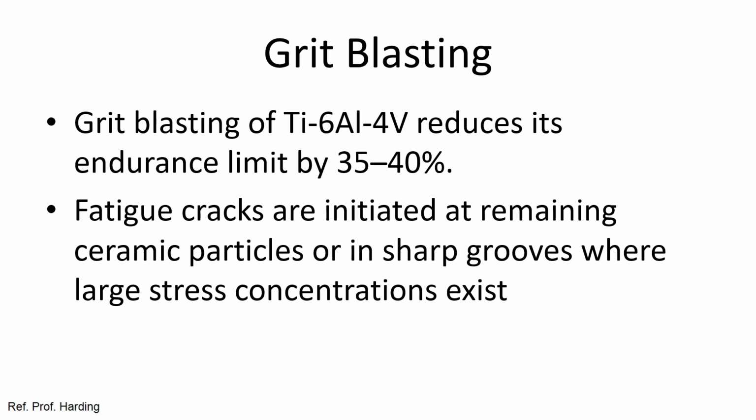And remember, grit blasting also removes material from the implant, so it affects the implant diameter, and a rough surfaced implant produces higher torques when it's inserted because it doesn't cut as efficiently. So although grit blasting has some biological advantages, it also has some mechanical and surgical protocol disadvantages associated with it. So what you gain with one hand, you lose with the other.